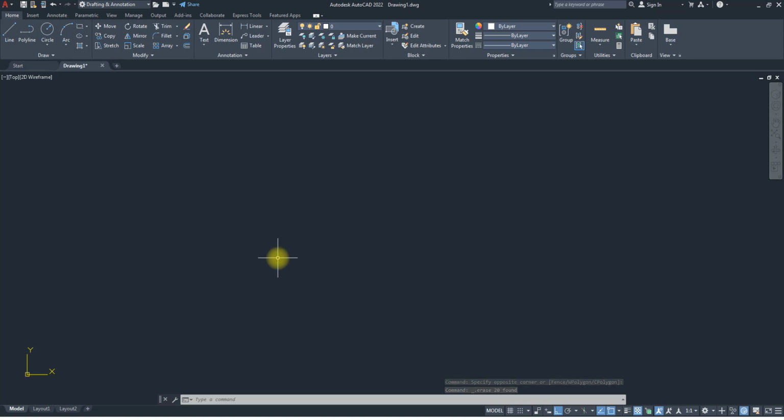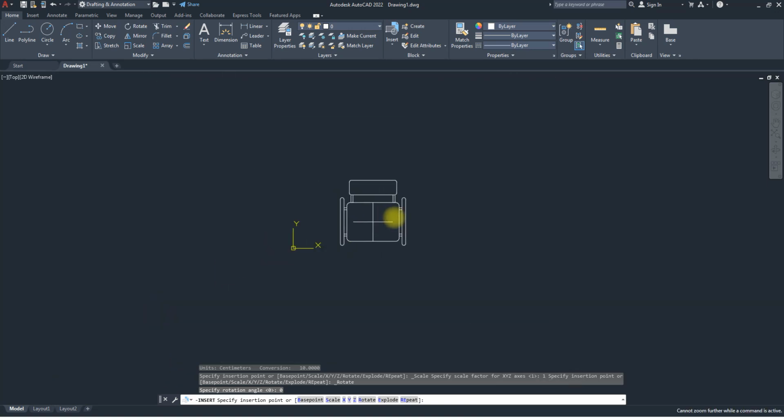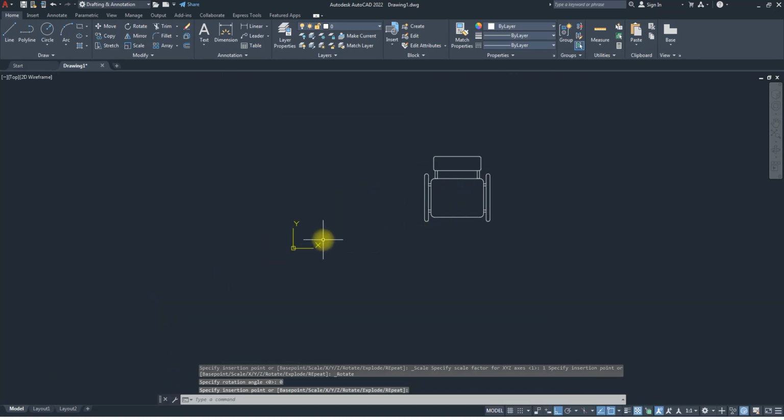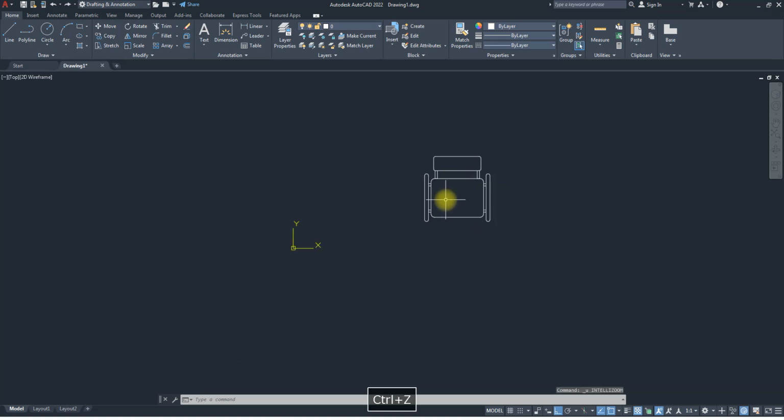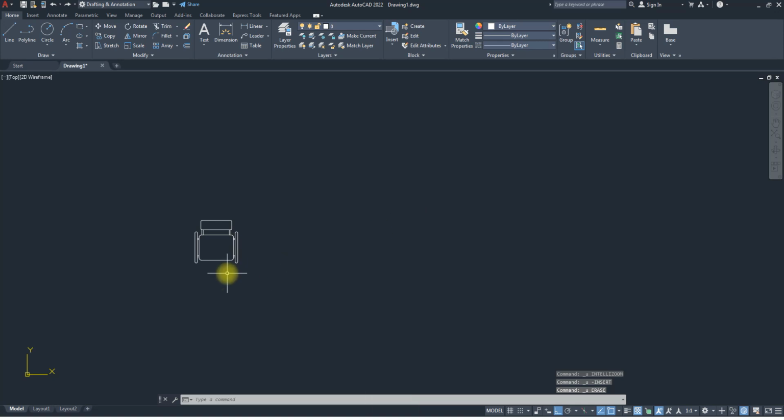So for us to now bring back what we have created, that will take us to how to insert. You can either use this shortcut I, or you can go through this icon. If you come to this icon, you see insert. And if I click on the arrow under insert, these are the two blocks I've created. Any one I choose brings it out. If I say okay, bring this table, it brings this table out, then I can drop it. You notice that the scale is kind of larger compared to before. Let me undo, so you see. Undo it till I have this.